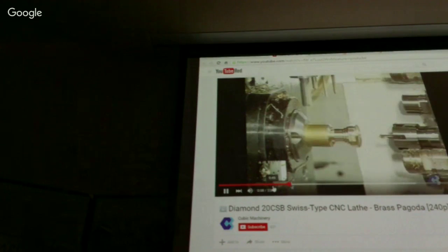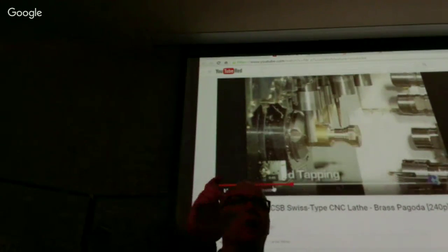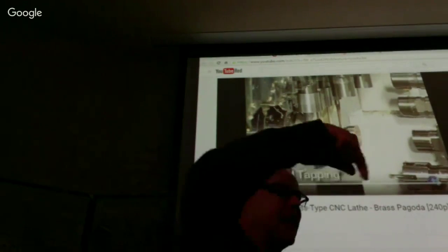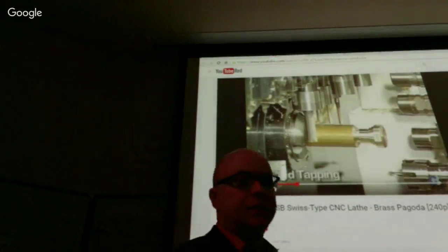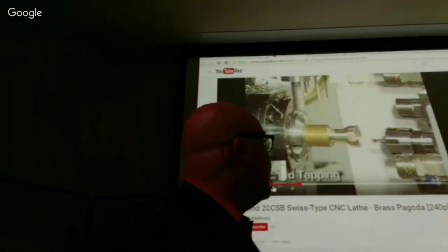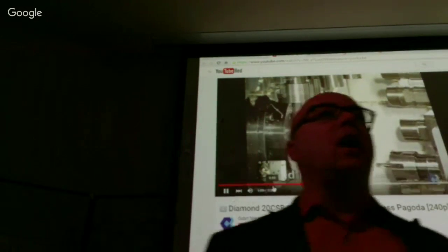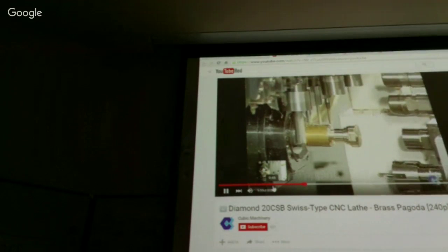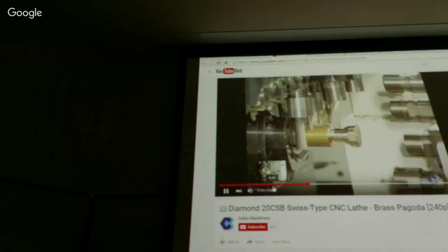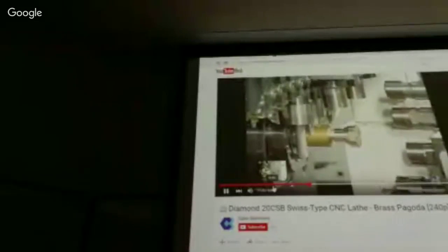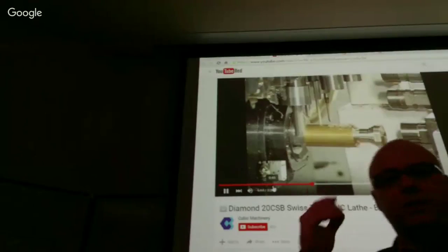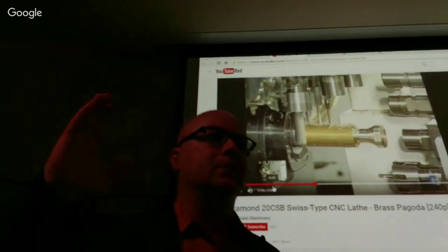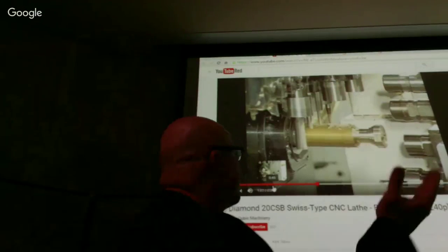So in this case, that part is rotating slowly, but the real cutting is happening because of the spinning cutter. The difference between turning and milling is that in turning operations, the workpiece is rotating. In milling operations, the tool is rotating, and that's what causes the cutting. So the cutting happens when the cutting edge of the tool moves through the workpiece material.